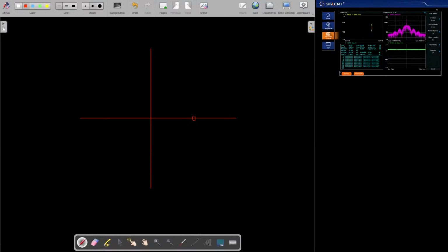We've got 1 point here and 1 point here. Of course, that's the in-phase and quadrature component. And 0 is, of course, at the intersection. That's the origin. So if you take the BPSK signal and record it and look at the baseband, long term, you get the DC component of 0 because both bits just cancel out. We assume, of course, that both bits 0 and 1 occur at the same probability.